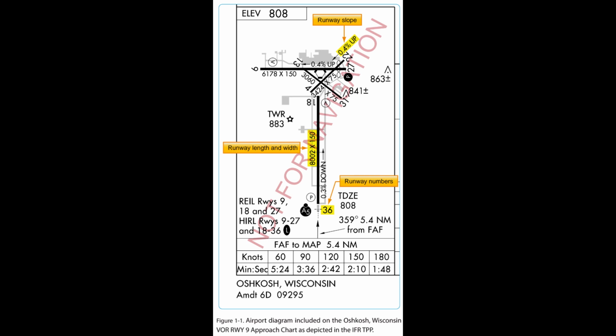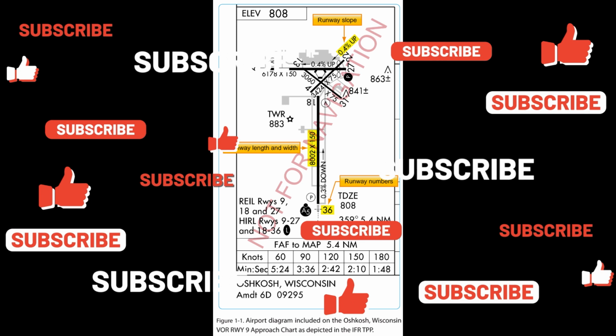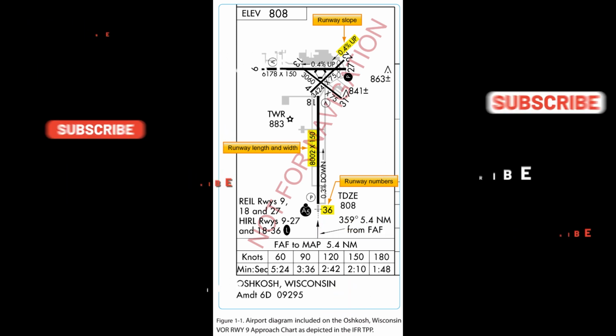Historically, takeoff minimums for commercial operations have been successively reduced through a combination of improved signage, runway markings and lighting aids, and concentrated pilot training and qualifications. Today at major terminals, some commercial operators with appropriate equipment, pilot qualifications, and approved operations specifications, OPSPECs, may take off with visibility as low as 300 feet runway visual range, RVR. One of the consequences of takeoffs with reduced visibility is that pilots are challenged in maintaining situational awareness during taxi operations.